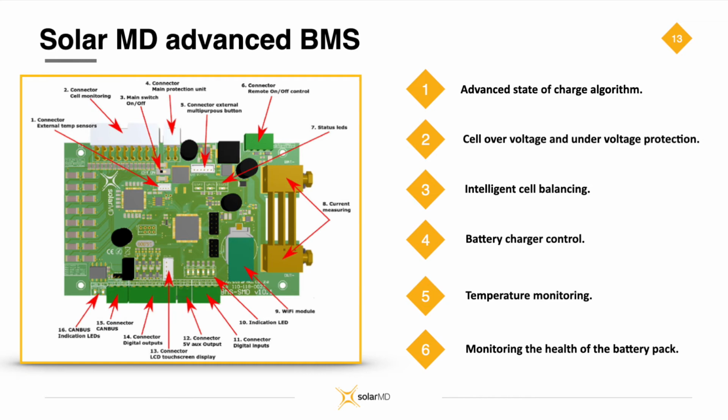The first 3 LEDs are yellow, to show discharge if current flow is selected, or less than 50% state of charge if capacity is selected. The following 3 LEDs are green, to indicate charge if current flow is selected, or more than 50% state of charge if capacity is selected. I will explain how to toggle between these functions when we look at the intelligent power button.